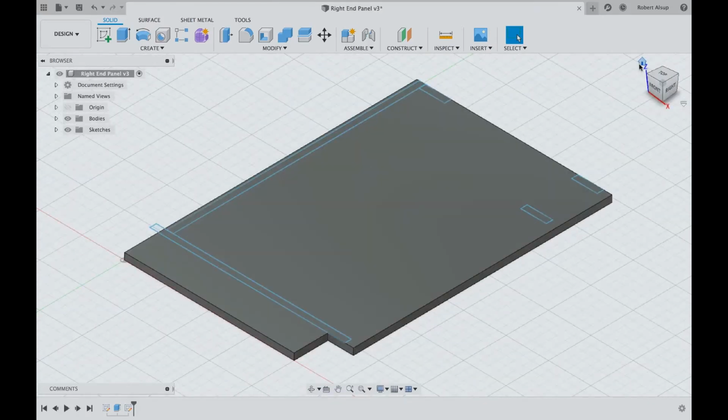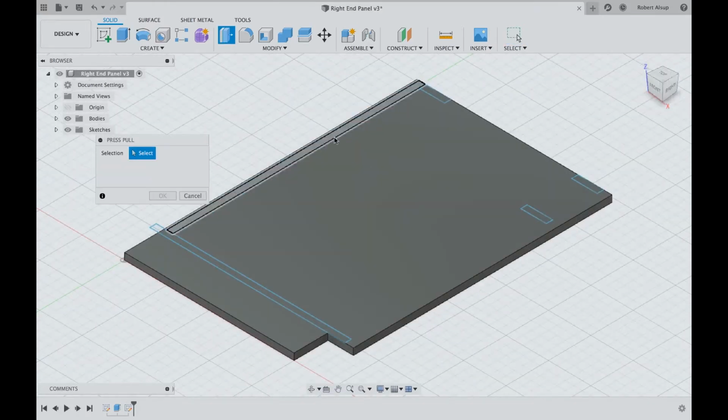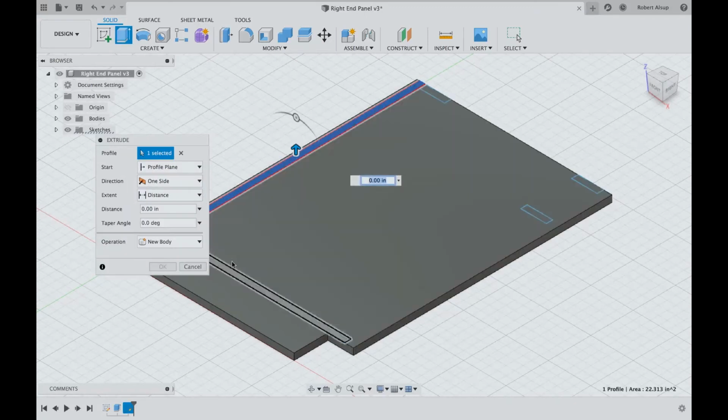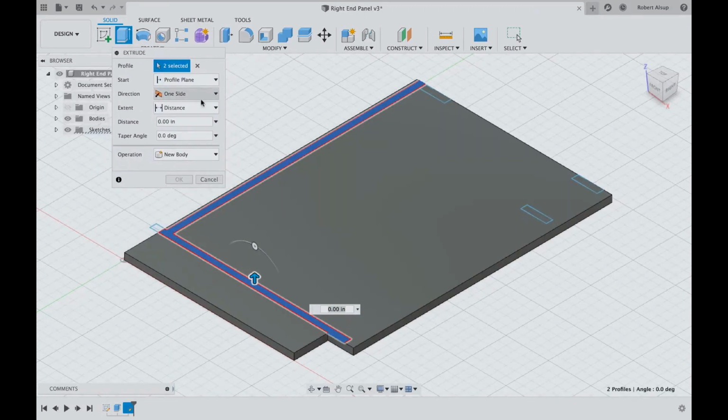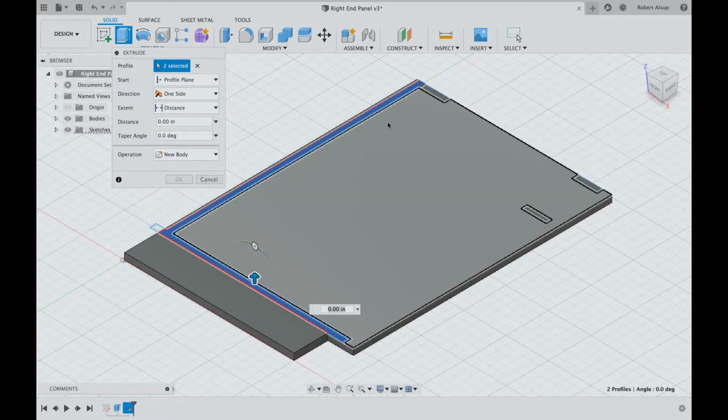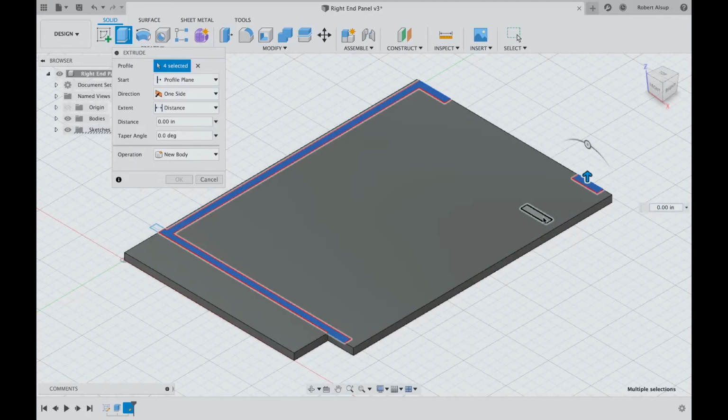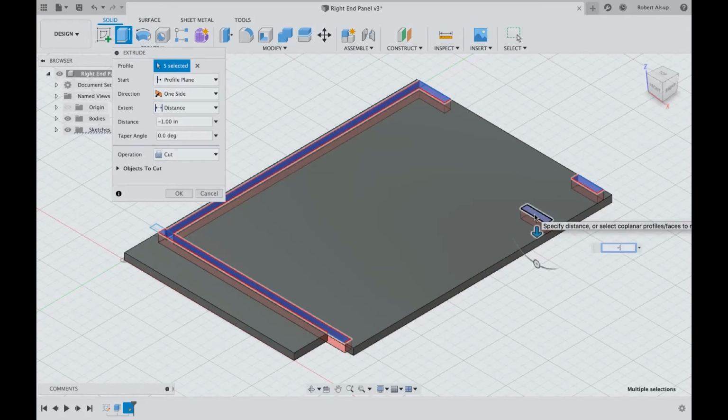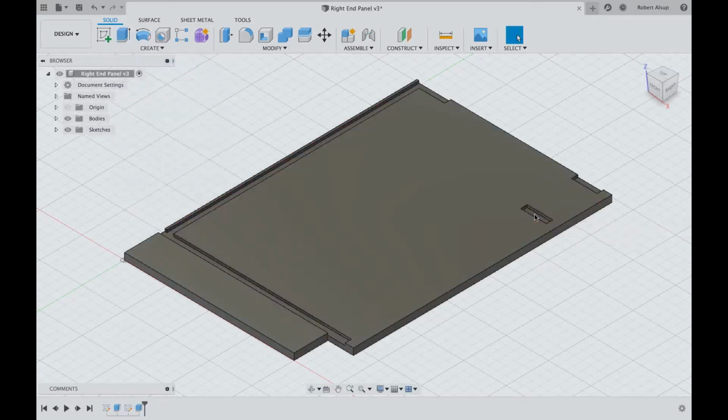All right, now we're going to hit Q. Okay, we're going to select that and that. Let's move this over to make sure everything's selected. Now you see how the part that hung over didn't get selected. Hit that and that and that. And then we use our arrow and set our dimension minus 0.25. And there's our dados. So that's how you create that part with the dados.